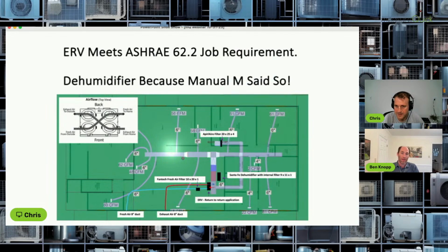But another benefit of taking a filter and increasing the surface area is that the air going through it slows down. The resistance drops by an order of magnitude. And now, nobody's perfect, sometimes a filter in the crawl space gets forgotten about for a little bit.